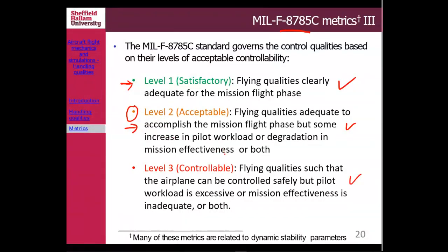As a designer, later on you will understand that you cannot really satisfy all the flight phases, right? You optimize your aircraft during cruise, but it might not behave the best during, say, climb. During climb, you think as long as it can still be considered acceptable performance, that's fine, and climb only takes about half an hour, maybe 20 minutes, 15 minutes, but the cruise takes hours, 6 hours, 5 hours. That's why a lot of designers try to optimize